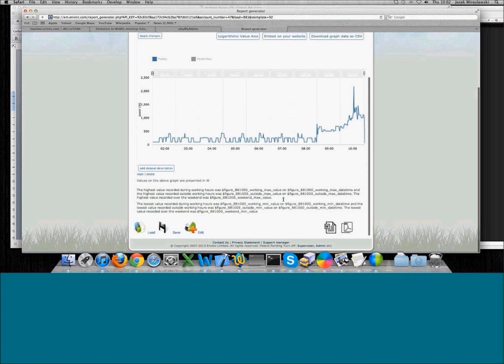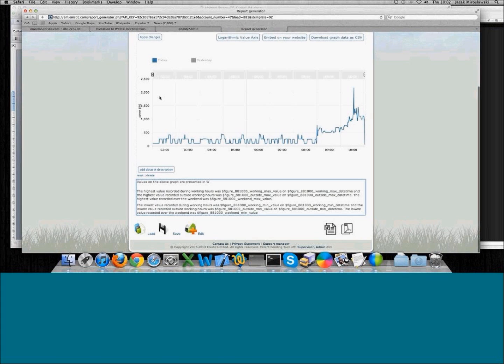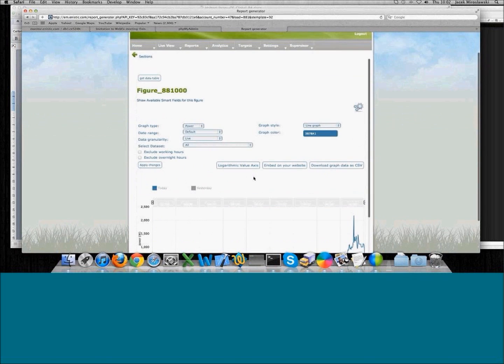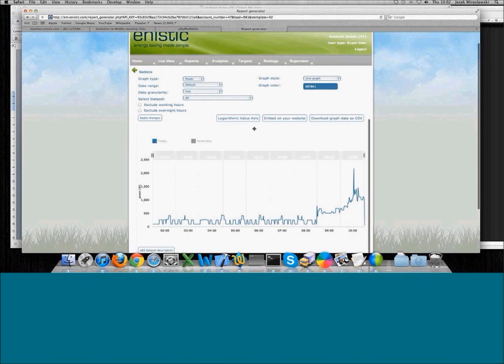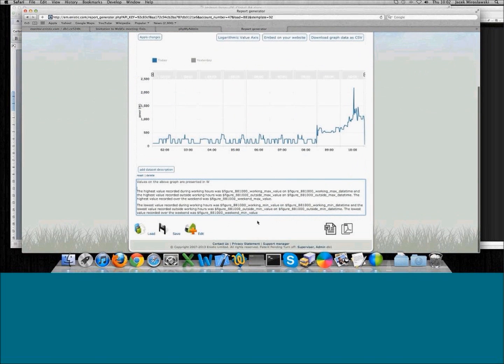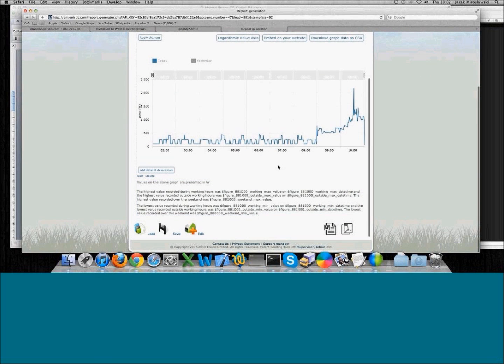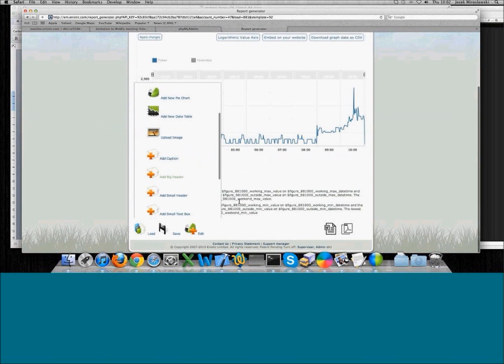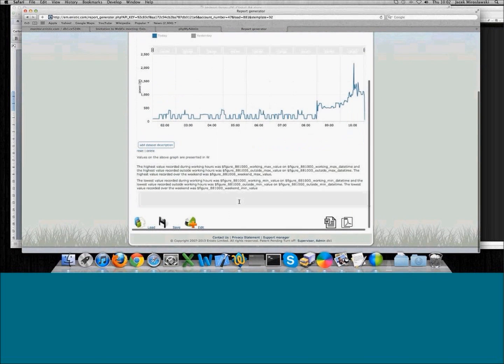And when we click on Run Reports, we can also edit sections further just for this particular report. Changes won't take effect until we press the Save button. So if we would like to add a new header, which as I mentioned previously will add a new page, we need to press Save to actually publish these changes into the report section.